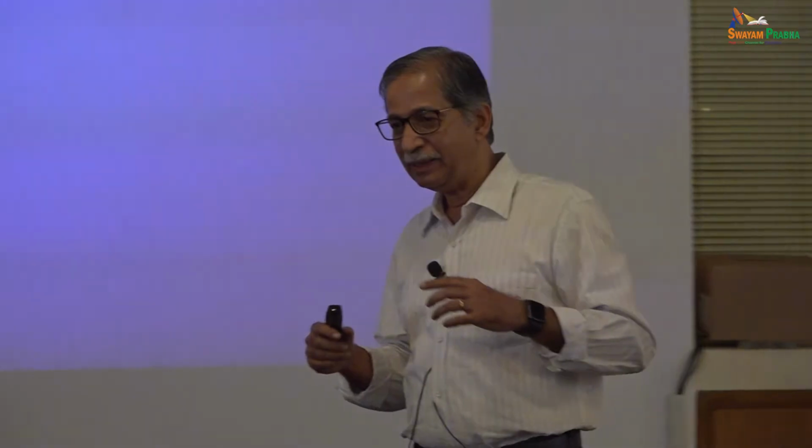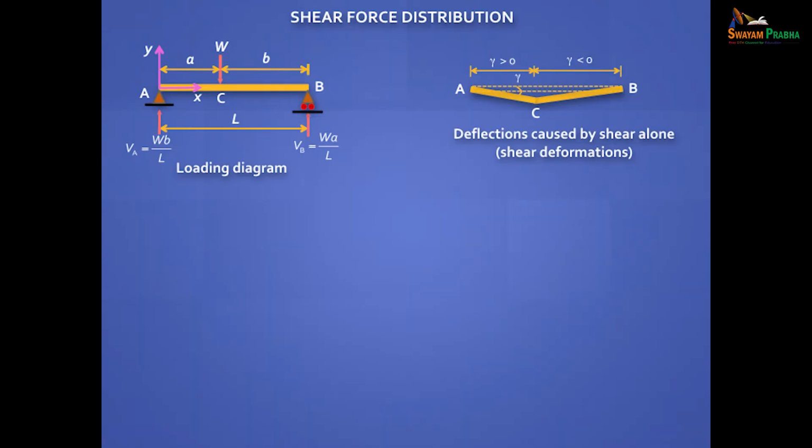When the depth of the section is comparable to the length or close to the length. Say if the length is 2 times or 3 times or even 4 times the depth, then don't ignore shear deformation. If it's 1 time, definitely don't ignore. But if it's a beam like this which looks well proportioned, span by depth ratio is about 10 or 12, then you can ignore this.